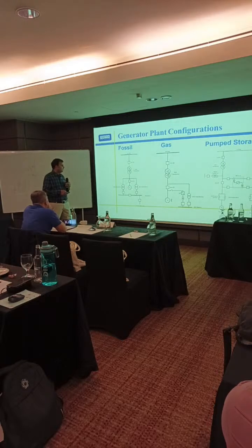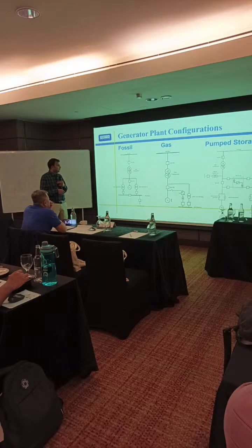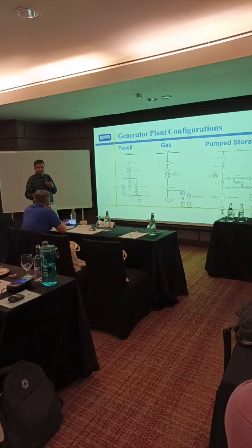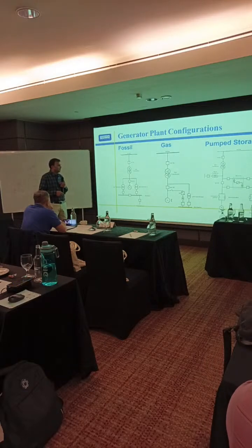In generator protection, there are many protections, you can see in the next slide. One of them is only generator differential. That is why what we learn in the transformer differential protection is all applicable to generator differential also. And it has only one slope. Why it has only one slope, we already discussed.